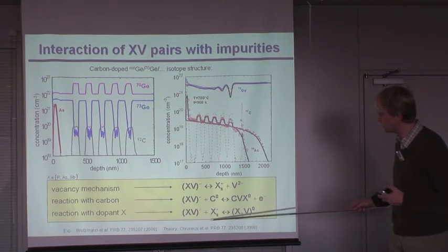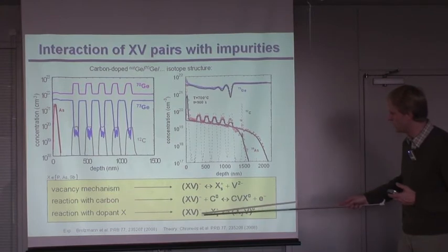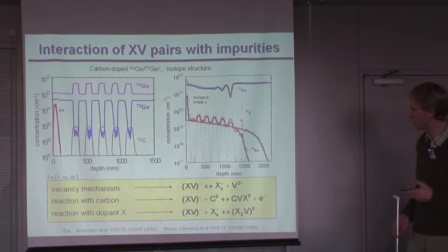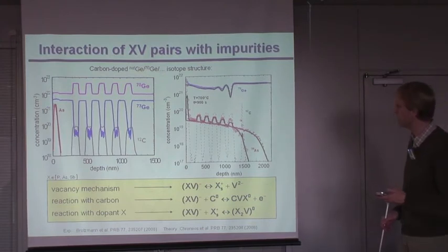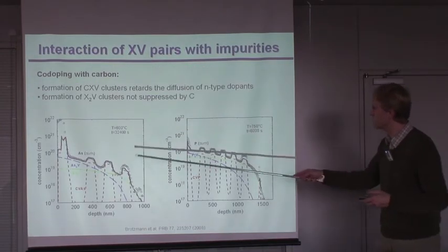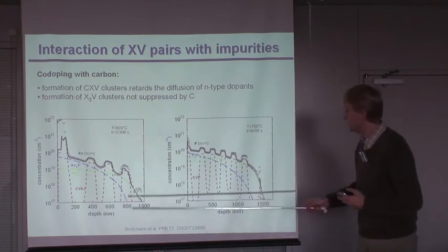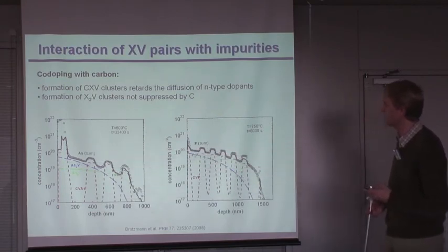So just due to Coulomb attraction, this negatively charged E-center pair tends to form a complex with the positively charged substitutional dopant. This ends up as a neutral defect, which of course is then missing in the activation of the arsenic, which is also a problem right now for the technology. Now you can do a simulation based on this model, and it explains the experimental results quite well.